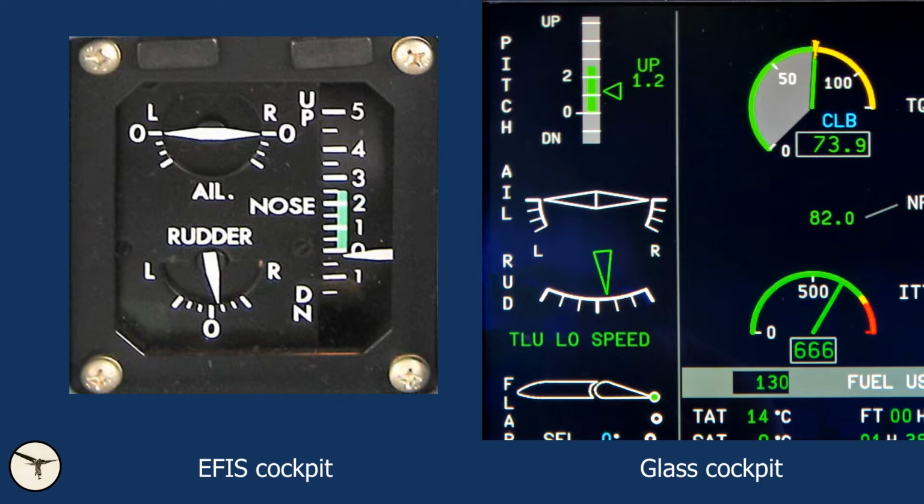The pitch trim does not have a mechanical backup. Instead, there is an electrical standby trim with a fully independent electrical circuit connected to the pitch trim actuator. The standby pitch trim switch is located on the pedestal. Manual activation of the pitch trim will disengage the autopilot.